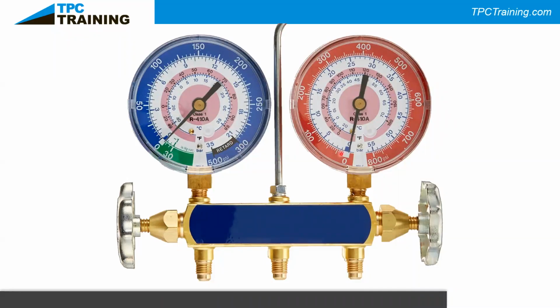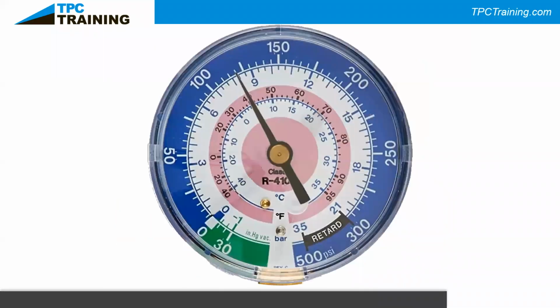The same thing on the high side: we're going to see it go from 0 to 800. These gauges are designed for the higher pressure R410A because they go from 0 to 300 and 0 to 800. If you have an older set of gauges that top out at 250 on the low side and 500 on the high side, they're not meant for R410A pressures. You have a potential of breaking your gauges if you put that higher pressure on them. So the PT chart is built right into your gauges for you.